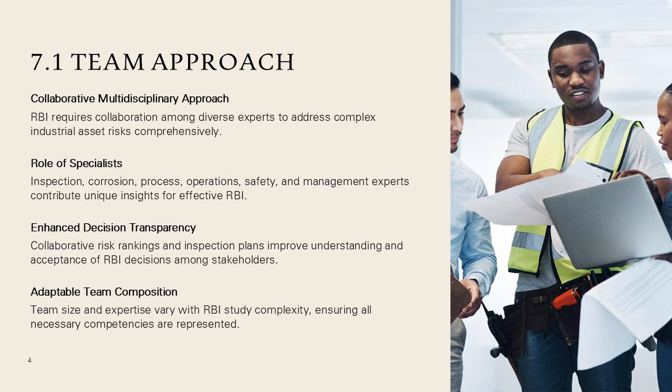API RP 580 recognizes that team composition may vary depending on the scope and complexity of the RBI study. Smaller or less complex systems may require fewer roles, while large or high-hazard facilities may require extensive specialist involvement. Regardless of size, the standard emphasizes that all necessary competencies must be represented and that communication among team members must be structured and effective. Ultimately, the team approach is foundational to achieving technically sound, defensible, and sustainable RBI outcomes.